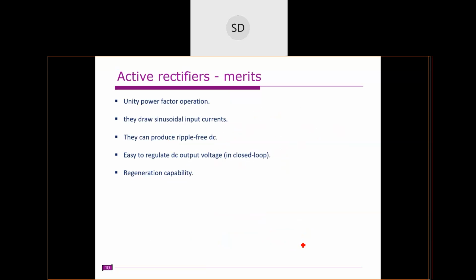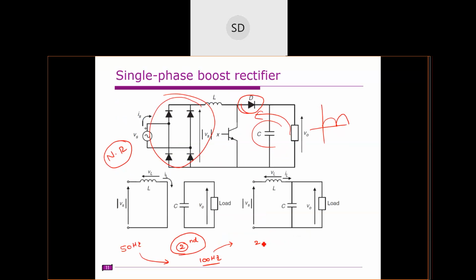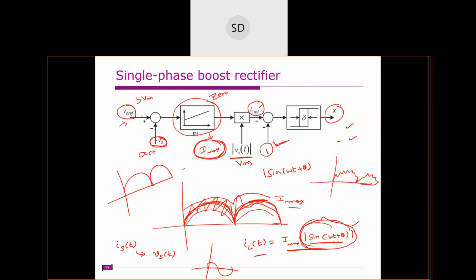We already discussed that when you have the second order harmonic on the source side, we have the fundamental and the third order harmonic on the AC side. So the second order harmonic in the output voltage, especially the output voltage produced in this diode bridge rectifier, will produce a third order harmonic in the input source current side. Therefore, the best practice is we need to eliminate this second order harmonic in the circuit.